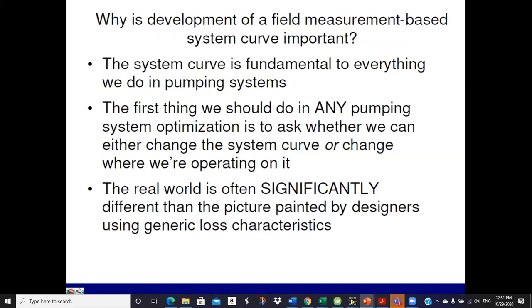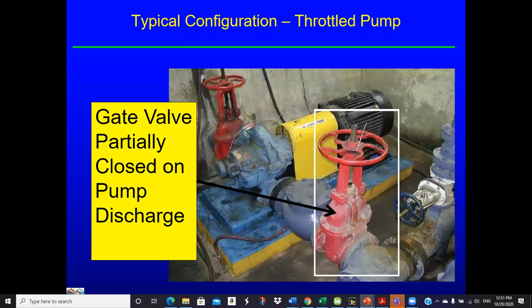Oh man, no, he ain't going there. If it's too big, no problem. That's what valves are for. And that's what we kind of rail against from an efficiency point of view. If you can buy it with a VFD, then you can buy the bigger pump, and then you slow it down with a VFD, and you don't incur the energy loss across the valves.